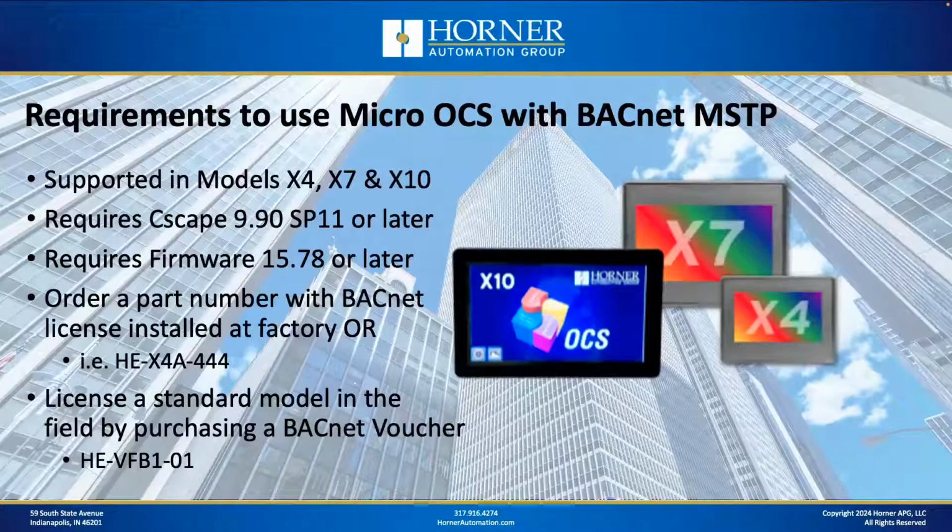First of all, if you want to use BACnet MSTP with the micro OCS, you're going to need to make sure you are using either the X4, the X7, or the X10. Now, I previously mentioned the X5. It has it built in, so that's also supported.